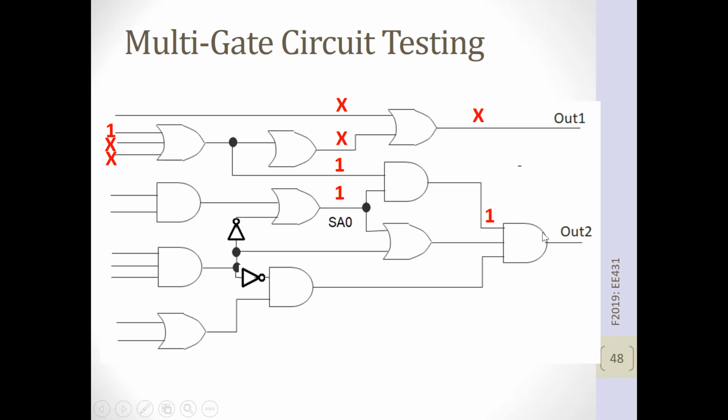When we want to pass that through, you need a 1 on both of these other wires. Otherwise, if there was a 0 on either one of these wires, it wouldn't matter what this value was. It would always be 0 on the output. So to make this a 1, if this is a 0, it goes through the inverter and makes it a 1.